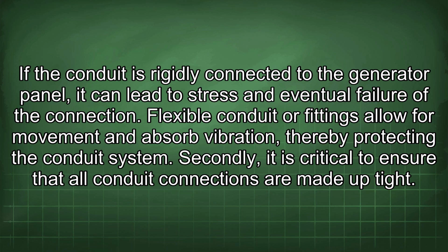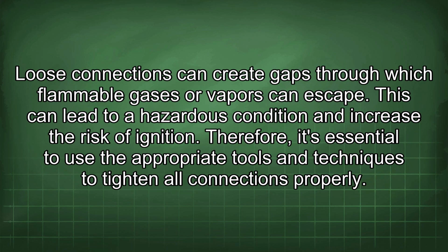Secondly, it is critical to ensure that all conduit connections are made up tight. Loose connections can create gaps through which flammable gases or vapors can escape. This can lead to a hazardous condition and increase the risk of ignition. Therefore, it's essential to use the appropriate tools and techniques to tighten all connections properly.